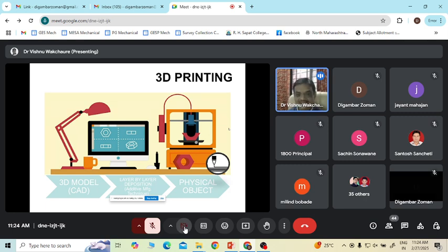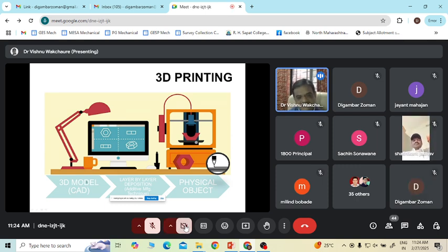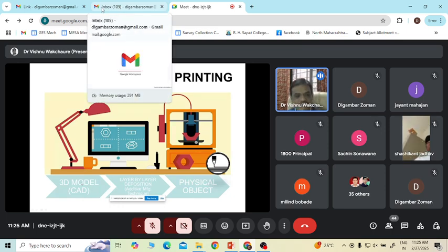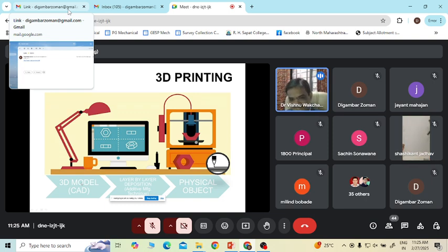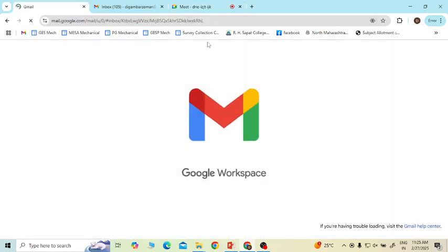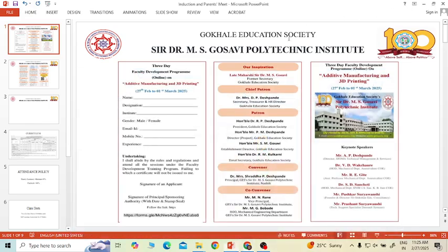In this figure and in the next figure as well, I will try to explain what the 3D manufacturing process basically is. In case of 3D printing or additive manufacturing, we prepare the 3D CAD model using any of the software, and we will have that data in the form of IGS files, STEP files, and likewise. Whenever you prepare a model using modeling software, that data is generated. So the first thing you need is the CAD model.